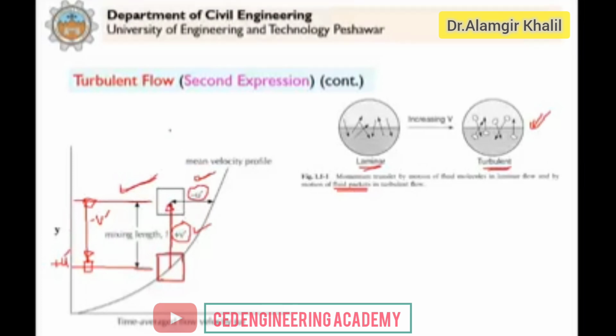So what we have is this u dash and this v dash, and then we average over a long time. So this is negative, clear? This is less than 0. So it will make the shear stress greater than 0. If you study, for example, the Indian books, you will not find that a negative sign is written. They directly proceed with that. But anyhow, according to our textbook, we need to put this negative sign to correctly represent them. Clear? So it means that the correlation is negative.